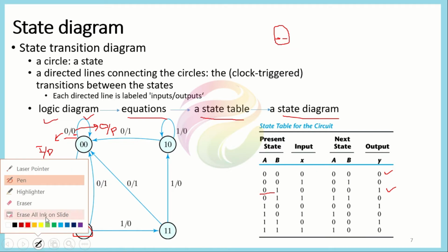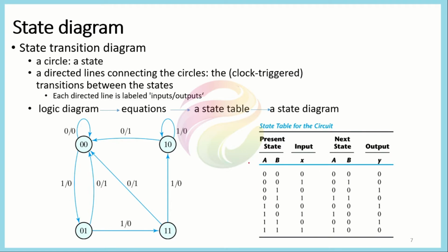So in this way, the whole equation of the system, which was first represented in the form of a table, is now represented in the form of a state transition diagram. Each entry here represents how our system will behave. This represents the overall behavior of the system, that is, what our circuit is performing.